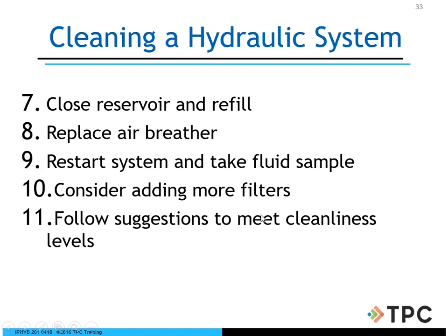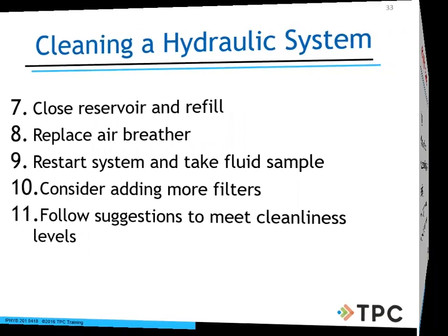On your filters, it is important to know what filter I'm actually using, a 5 micron or 10 micron. Am I using a surface type filter or a depth type filter? Am I getting nominal filtration, or more absolute filtration? These are terms used in the hydraulic world as we move forward.